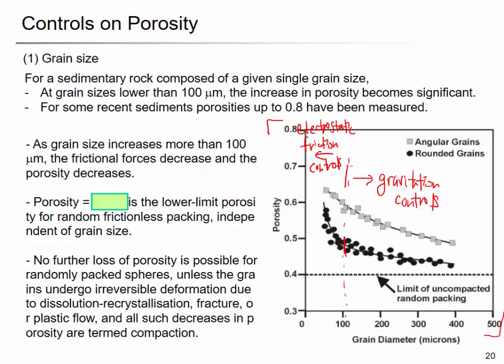They say it's 100 micron, but we know a more specific number from the Unified Soil Classification System. What is the particle size threshold between the fine and the coarse grain? What sieve do we use? Number 200. And what's the opening size of the number 200 sieve?